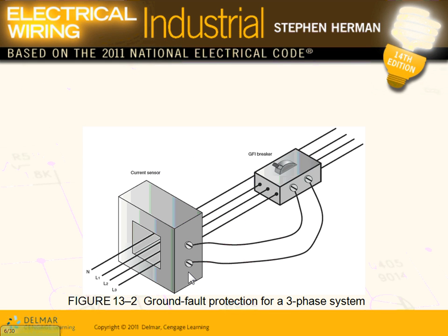Okay, Chris, ground fault. Here's how the ground fault works. You have a circuit breaker. This is a 2000 amp circuit breaker. It's 480 volt slash 277 volts, right? Is it required? Yup, because it's more than 1000 amps and the voltage is 480/277.